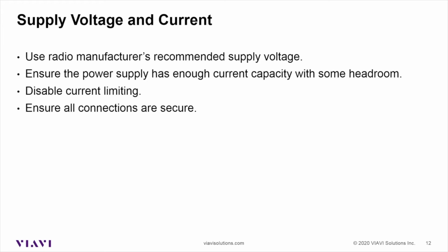So not a lot of current capacity in that short span of wire. Now, normally I wouldn't expect that to cause a huge problem, but in this case it actually caused enough voltage drop that the radio was sensing that. Radios monitor the voltage sometimes, and if they do, and they see that lower voltage, they may go back into a lower power mode.